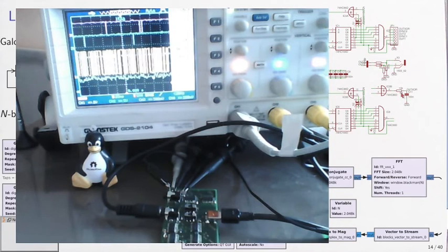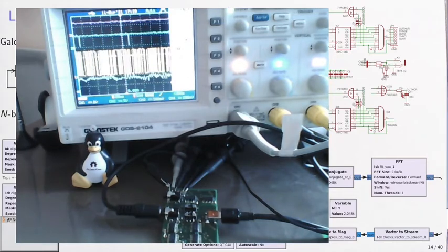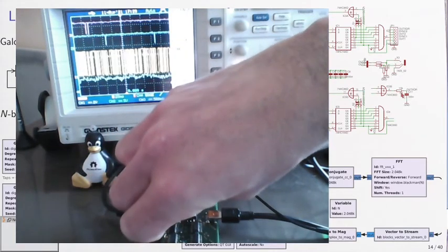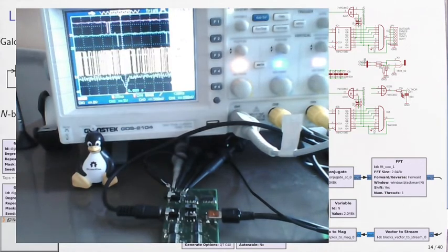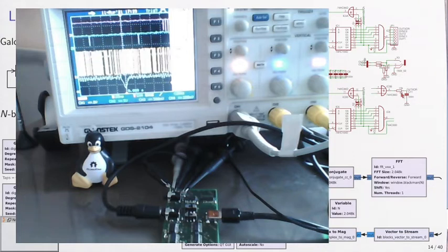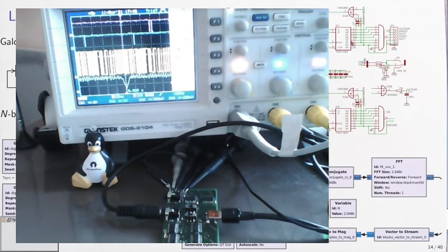And what we see here is that now the two pseudorandom sequences do not match and there is no correlation peak anymore. If I go back to the original sequence and back to normal, then I have a correlation peak again. So you see how easy it is to generate using these linear feedback shift registers with the appropriate tap positions, which can be easily shared between users. If I define the length and the tap position, I have defined all the parameters of the communication scheme.